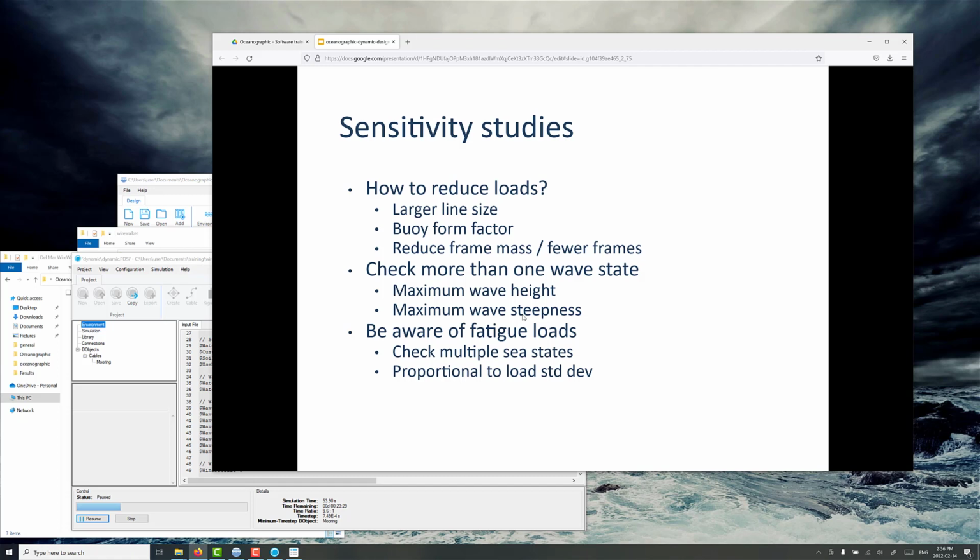The biggest wave heights seen in the Southern Ocean from this mooring were on the order of almost 20 meters. But the periods were so long that they just weren't that steep, and they didn't really create a lot of dynamic loading in the mooring. It was more like the significant wave height around 10 meters which had the biggest steepness and the greatest acceleration on the buoy, and then the resulting mooring with the greatest dynamic loads that caused the problems.